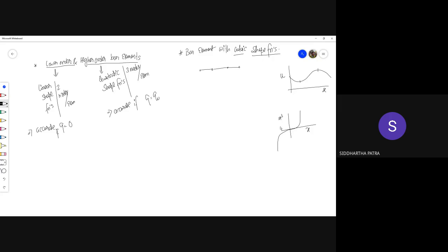So maxima from this side and minima from this side, but they have two of them in general. Now I can come up with 4 degrees of freedom for a single element, namely u1, u2, u3, and u4, while I could number the shape functions as N1, N2, N3, and N4.